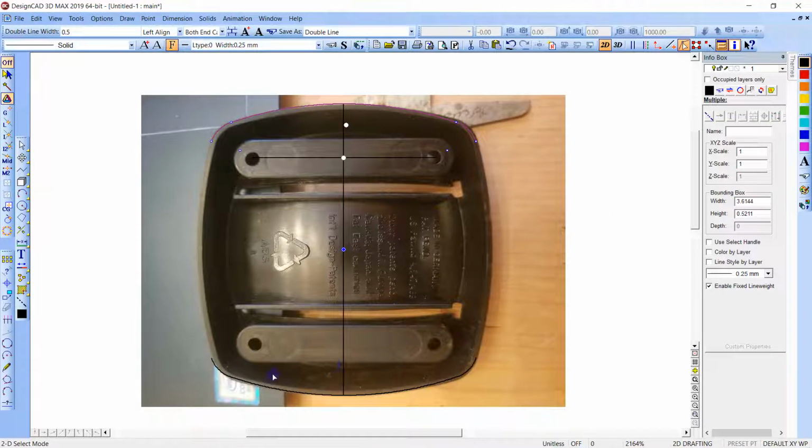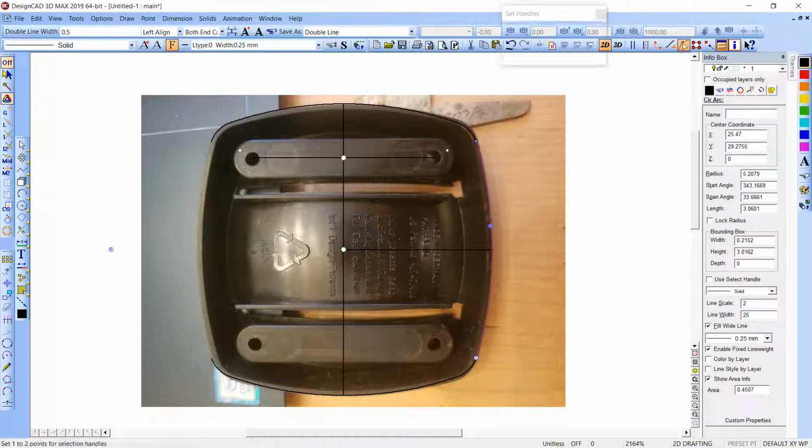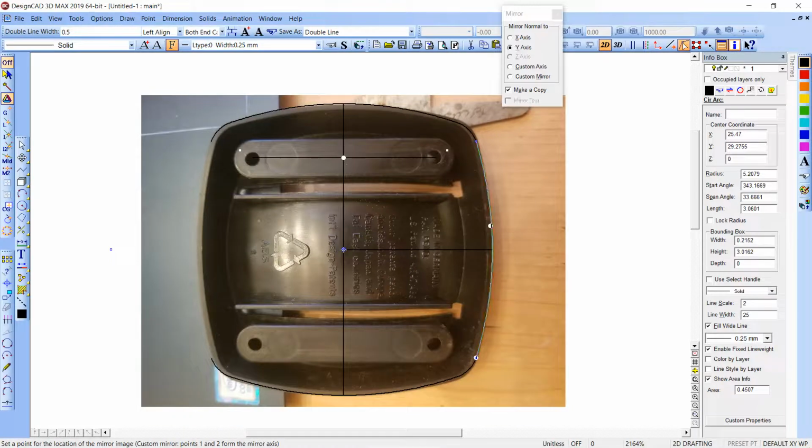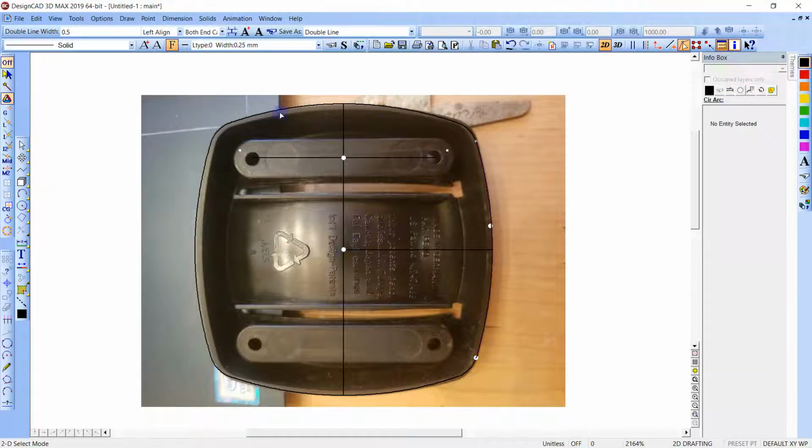So now I have the top and bottom with the radiuses, and then I'm going to do V, H, same thing I did, H. I'm just going to go to the end of that. And then I'm going to do a 3-point here, right click on there, H, right click to the center, and right click to the other radius. And then we're going to click that radius, Control H, right click to the center, and reflect that in the X direction. And now we have something that's nice.